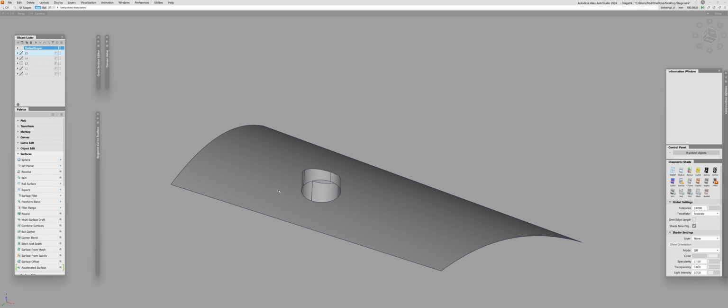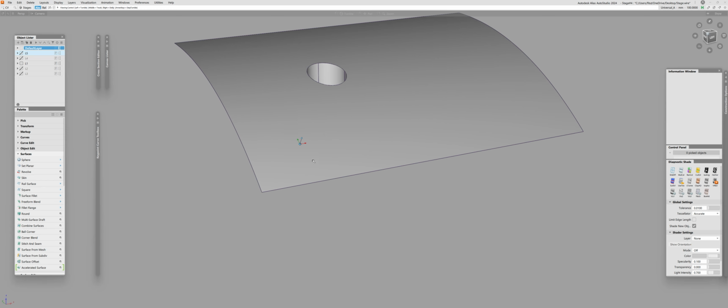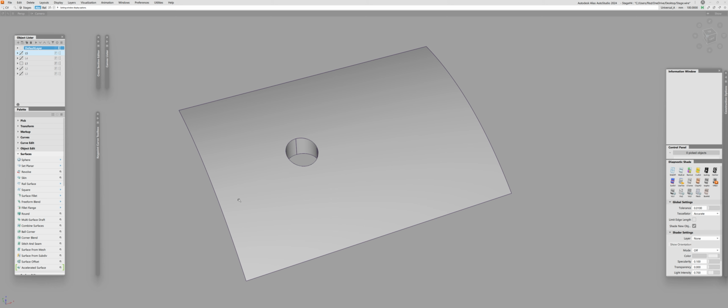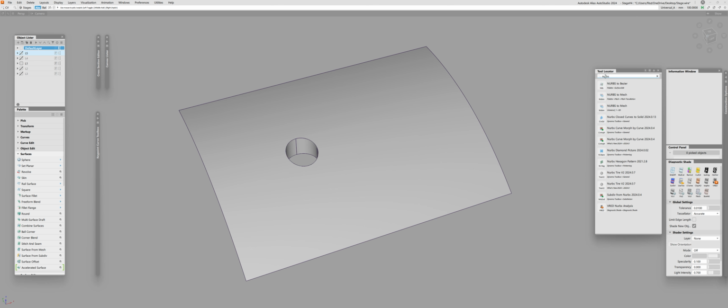surface with a cylinder. And actually, we can easily visualize what's going on under the hood and what structure it has. For that, we have a tool which converts the underlying structure which we have right now to a mesh, not in real time. I basically bake it to actually have the actual mesh with no link to the underlying structure. To do so, I use the hotkey Ctrl F. I believe it is a universal hotkey. It should work for you regardless of what hotkeys you changed everywhere else. And I will type NURBS, and that is NURBS to mesh. This is the one we're looking for.